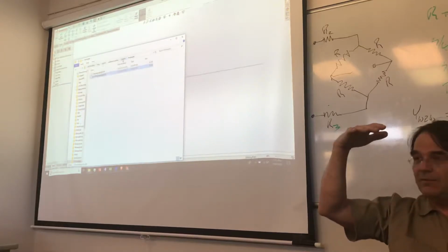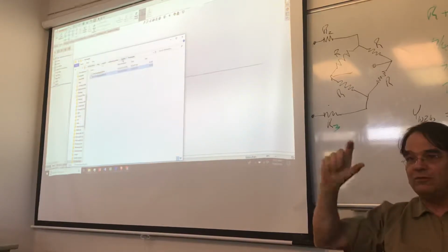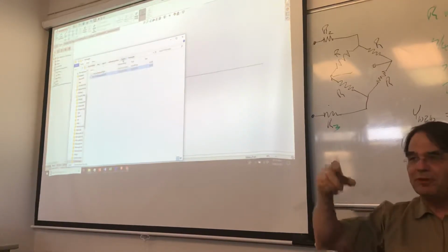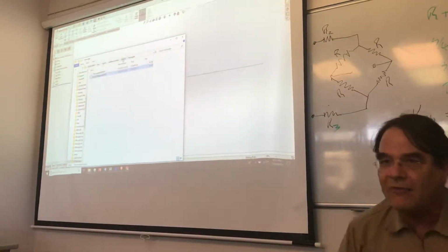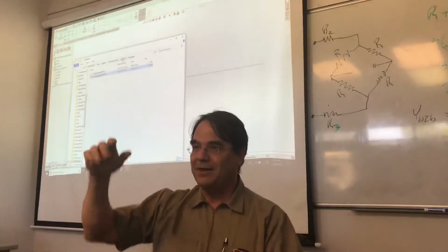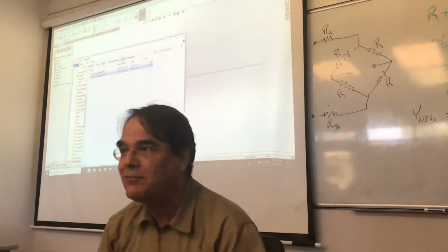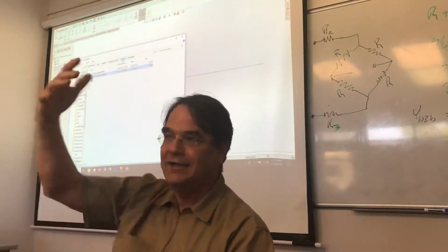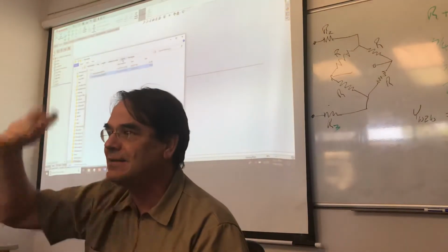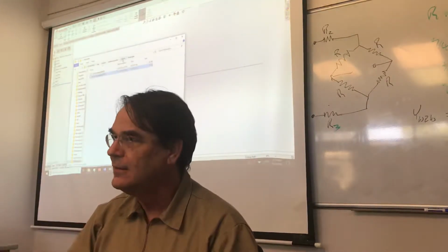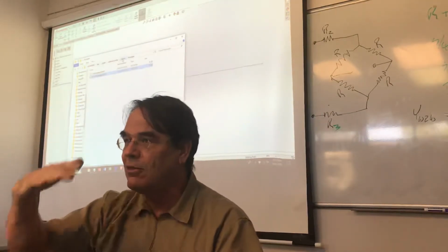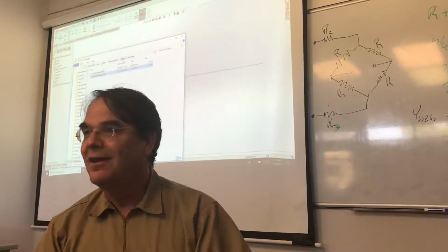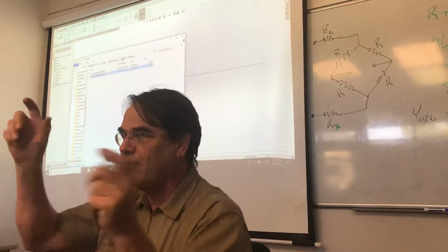So the file that you created, the library feature part, needs to be 2 levels deep after the weldment profile one, because there are 2 tabs that you're going to have to pick, right? In this case, we pick a rectangle one underneath our custom one. We make our custom one, and then we make another level of directory, so we have a directory tree.